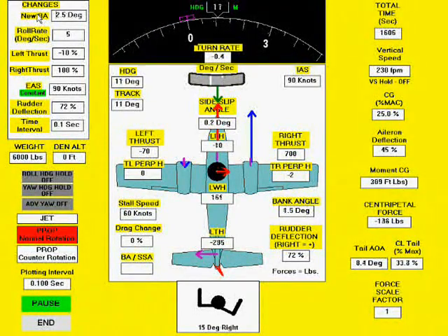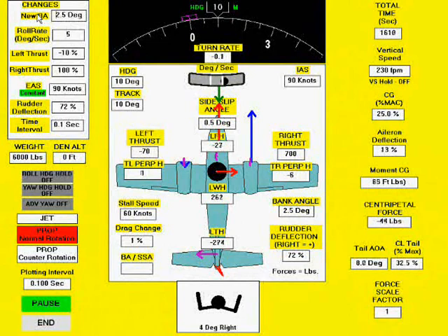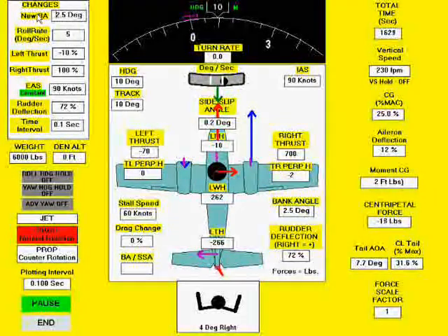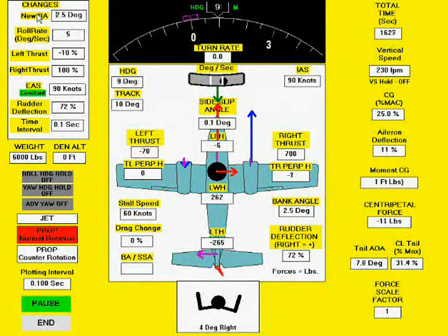The significance of this effect can be measured by taping a yaw string to the nose and observing the wheel position when the sideslip angle is zero. Since this effect is typically small, the jet procedure for identifying the failed engine is just as effective for prop airplanes.